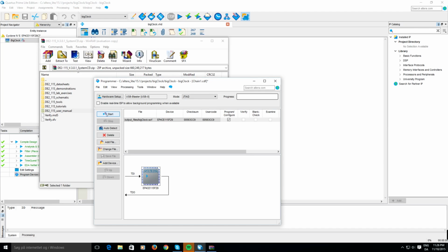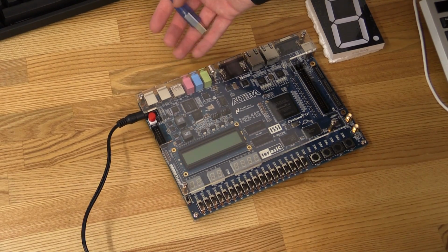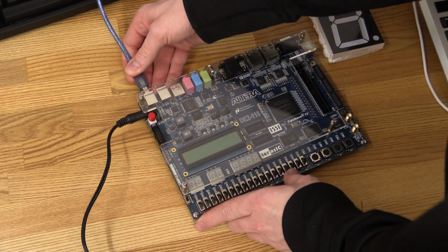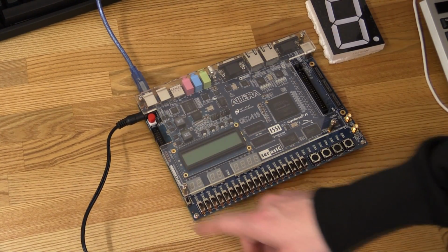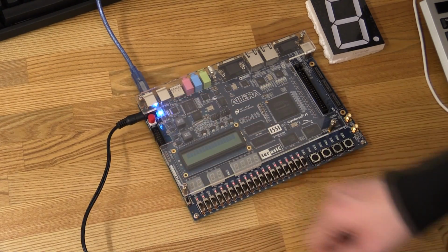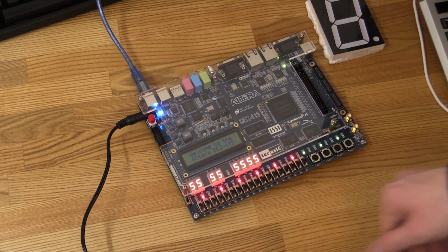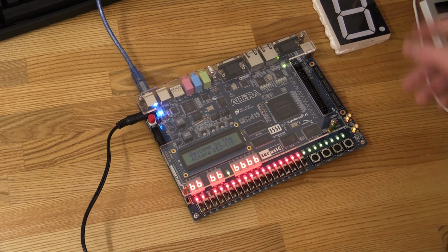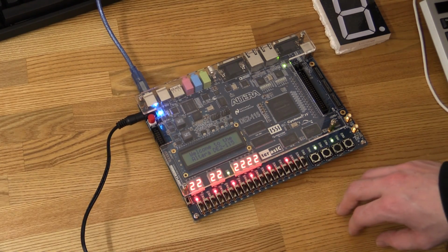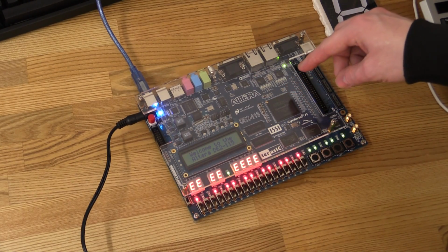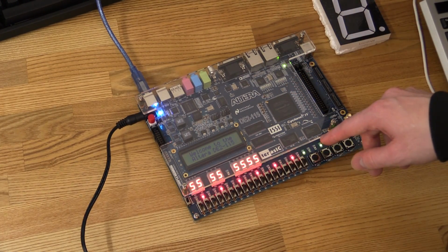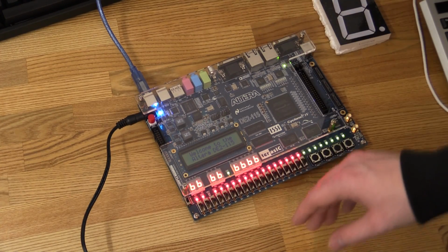And I'll just switch to the camera so we can see the board, and then we'll press start. We put the USB cable into the USB Blaster input, and then we turn it on, and there's this standard program on the board. And what we're doing is actually just reprogramming the FPGA. We're not putting the program onto the flash memory just yet. We'll do that later.